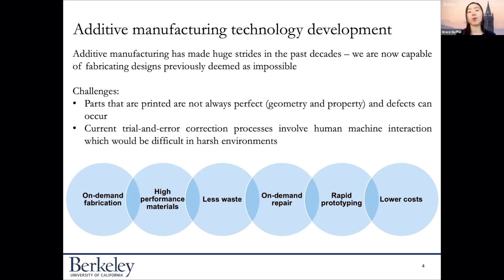What we have realized in the literature is that what dominates these defects is how you choose your process parameters. All those printing parameters, like printing speed, power input, and the flow rate coming out of your nozzle, dictate how well it prints.